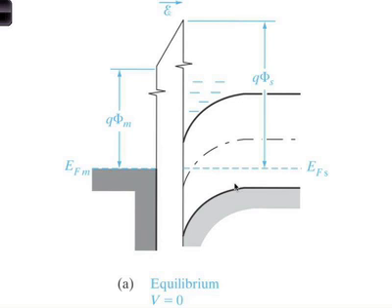Okay? Now, of course, we can avoid this problem by simply choosing a metal whose work function is larger and closer to the work function of the semiconductor. Now, the choice of metal, although there are several metals to work with, it's not infinite in the sense that there are some metals which are easier to process, and we'll talk about processing in Chapter 9. But there's some metals which work well at low temperatures. You don't need high temperature processing, all that kind of stuff. So that kind of restricts what you can use for the gate material.